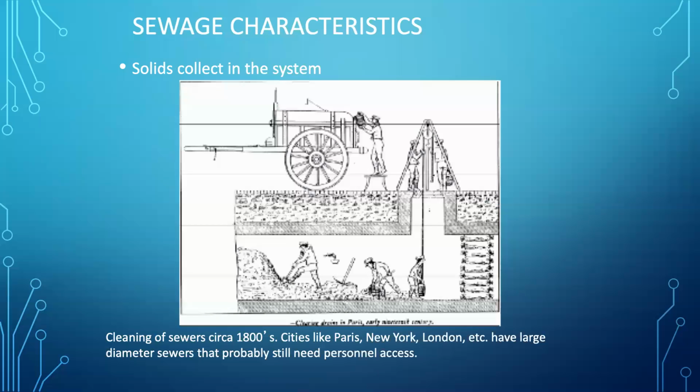The solids present an interesting challenge because even though they're not a large fraction of sewage, it's flowing day and night. So as long as there's people living 24/7, they'll be producing biosolids, and that goes into the sewage system. And those solids, in some locations, collect because the flow velocities drop below a sufficient velocity to sustain their suspension, or well, pretty much that's why.